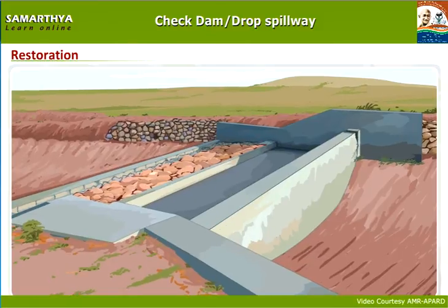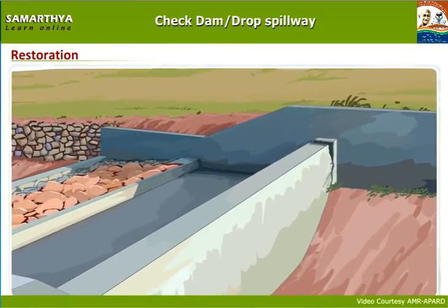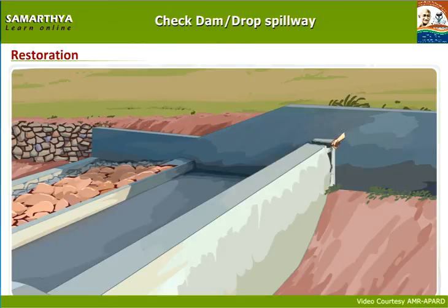When there are small cracks, joints between body wall and guide wall must be removed completely. If the plastering is done without removing completely, cement may not stick in the cracks and leakage may develop again within a few days. After removing, clean it with water.